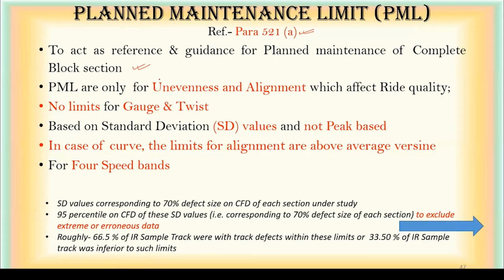Again, PML, since it is not going to affect safety of our track, no tolerance for gauge and twist has been given. Only unevenness and alignment defect has been given, and that too only SD value.